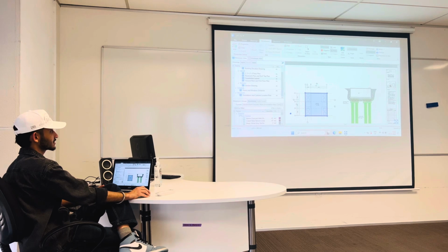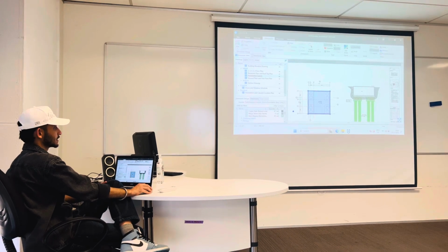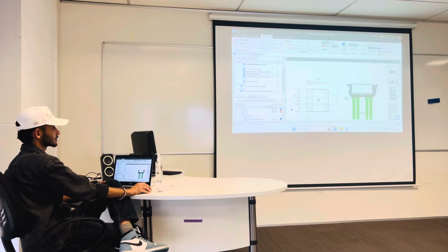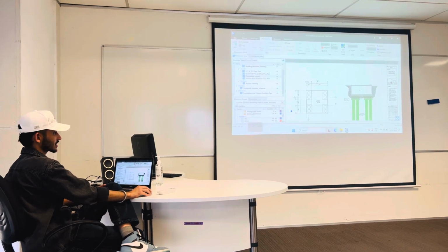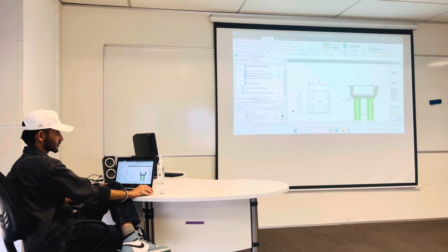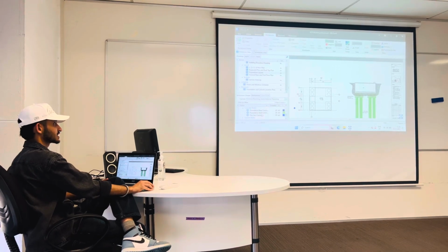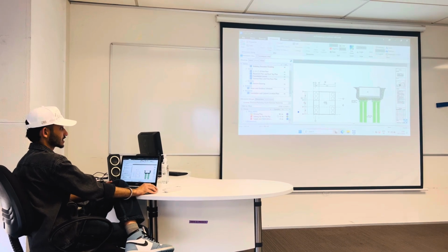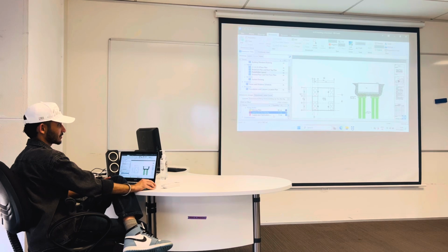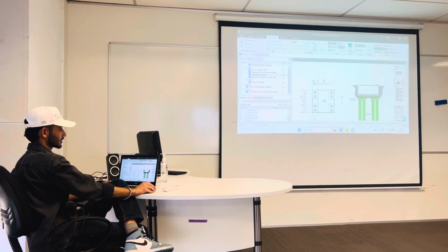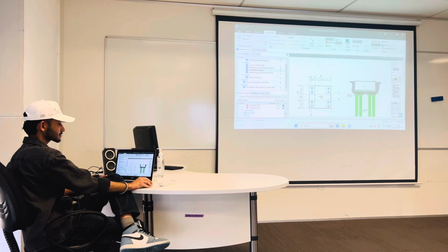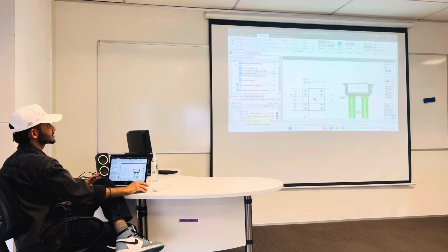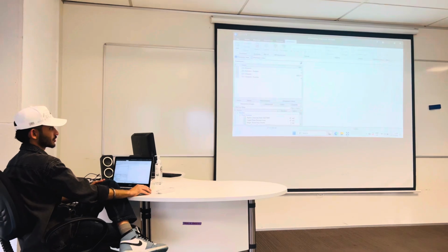In this project we have the finishes, floor finishes, plastering works, skirtings. We have calculated the gross floor area as well, used floor area. Then there is foundation base concrete, and these all are the dimension groups we have selected, and we have calculated and measured all the dimensions and the sub-dimensions. After you have measured all the quantities, the next step is to make the workbook or the SOQ.